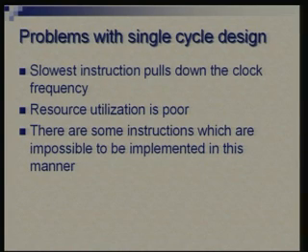We have an ALU sitting in one place, but we have put 2 adders for doing an operation which the ALU could have done. So the question is, is a design possible where we don't need those extra adders? Can the ALU do everything without loss of performance? We would need to answer that question.